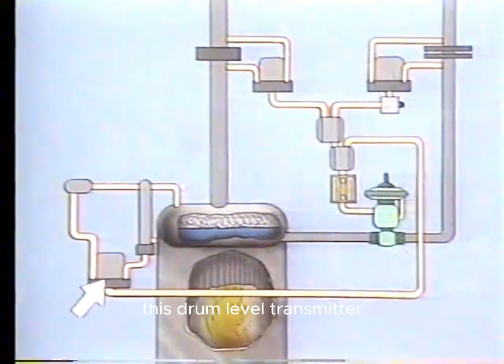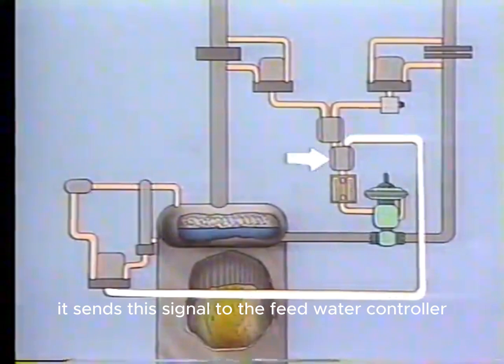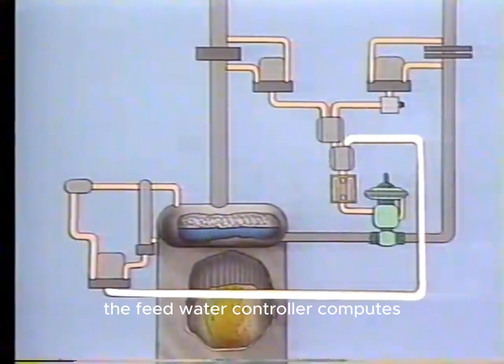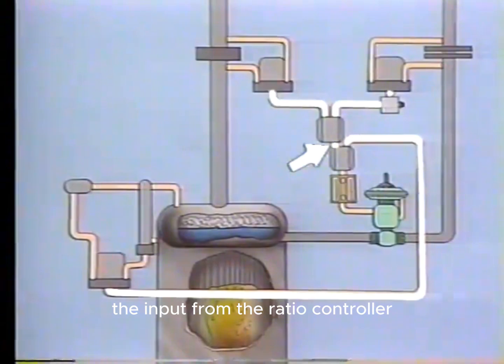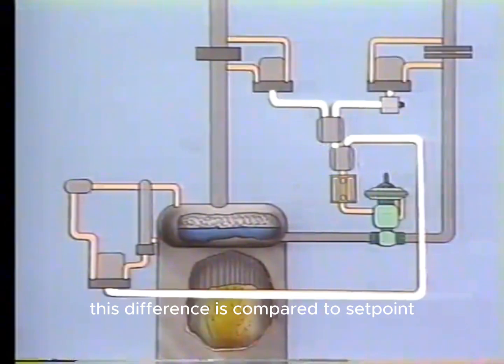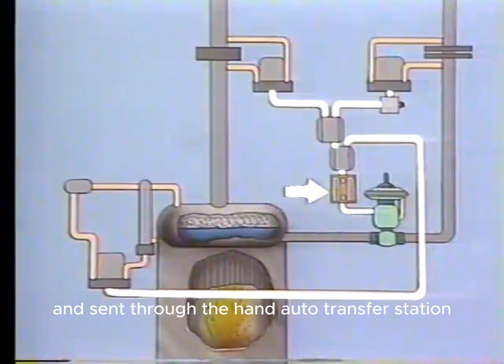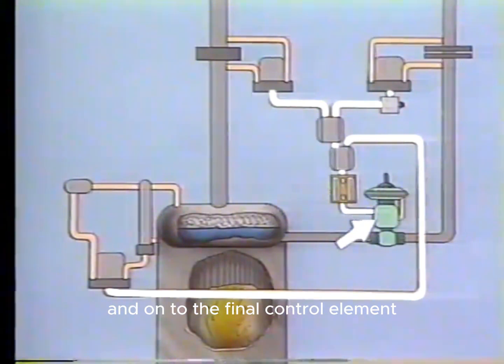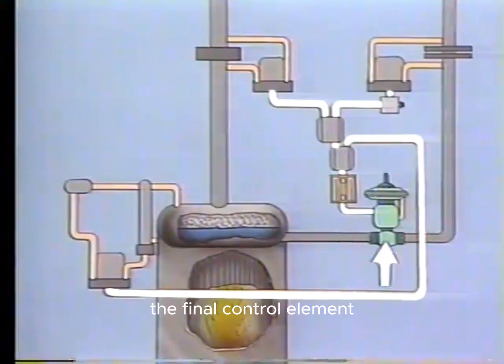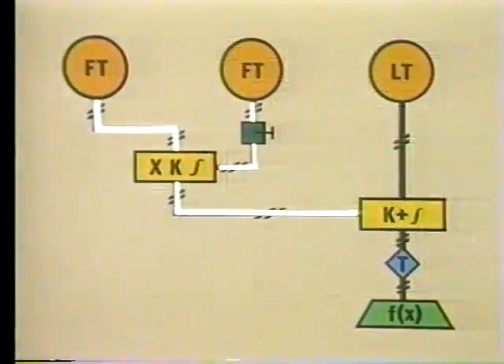This drum level transmitter produces a signal that represents the level of water in the drum. It sends this signal to the feed water controller. The feed water controller computes the difference between the input from the ratio controller and the input from the drum level transmitter. This difference is compared to set point, and a corrective signal is produced and sent through the hand auto transfer station and on to the final control element. The final control element positions the feed water flow control valve to regulate the feed water to the boiler drum. Looking again at the logic diagram, we can learn more about the instruments we just discussed.